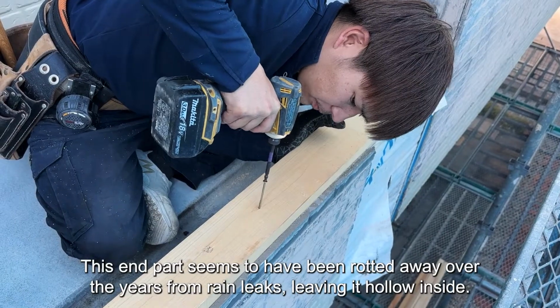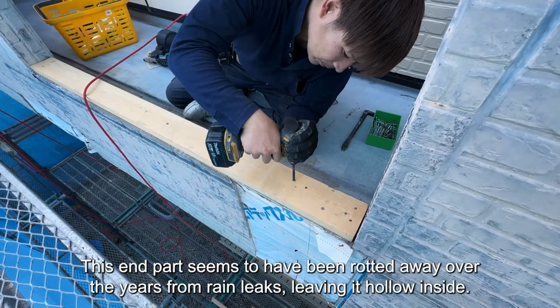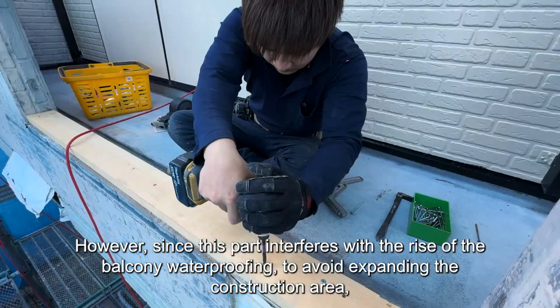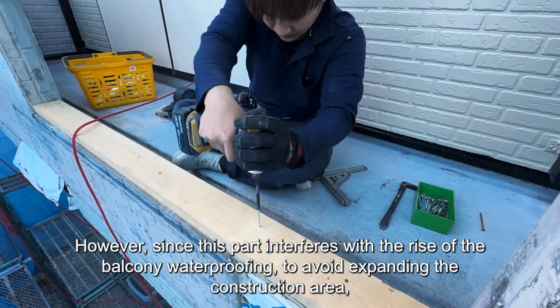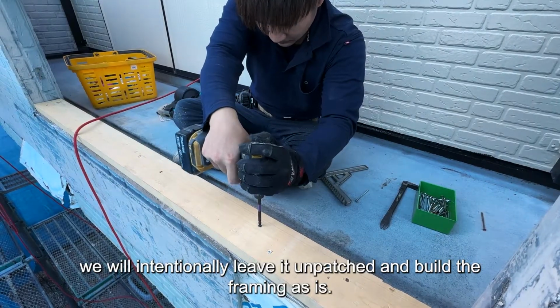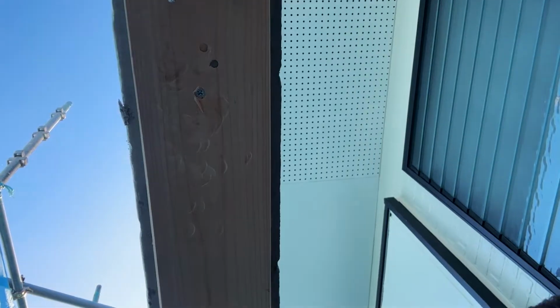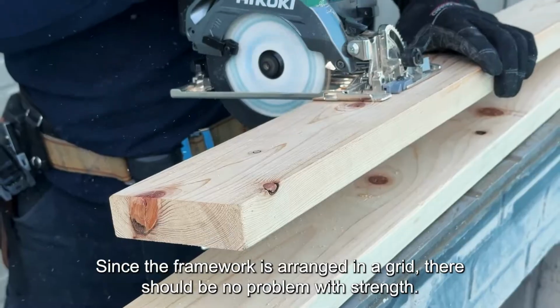This end part seems to have been rotted away over the years from rain leaks, leaving it hollow inside. However, since this part interferes with the rise of the balcony waterproofing, to avoid expanding the construction area, we will intentionally leave it unpatched and build the framing as is. Since the framework is arranged in a grid, there should be no problem with strength.